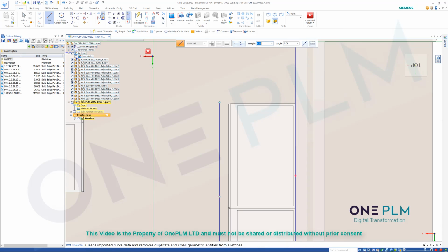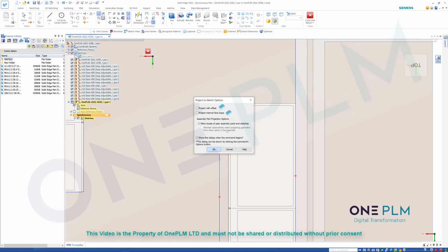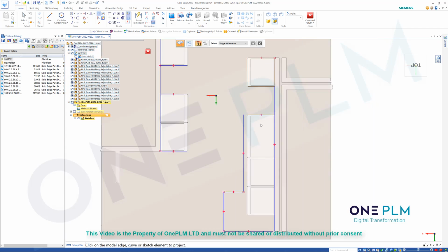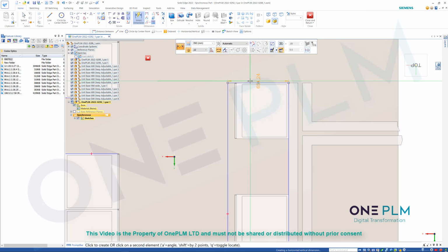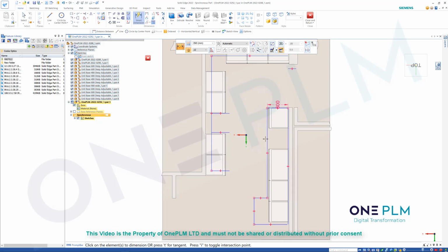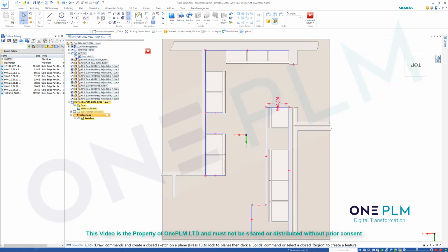And then this one, I probably should have actually taken this first. Okay, well, that's not the one I wanted, is it? Because I've got an under unit in there. And if I use the trim corner, it might be under a drop down if you're not using customized theme, but I've gone and taken that, and I'm just going to make sure that that is 600 deep on there. So we've got that. I'm just going to go and make a quick change on here and turn my auto scale sketch off, which I don't want for this instance.